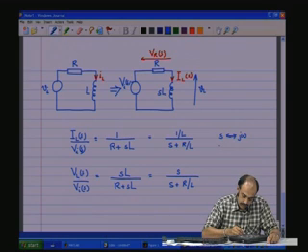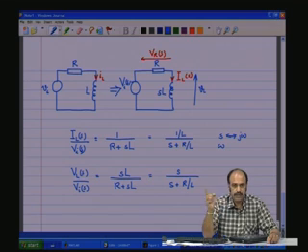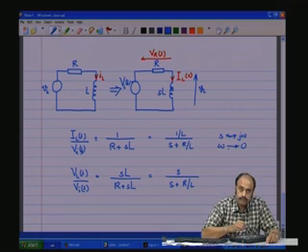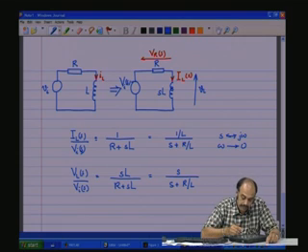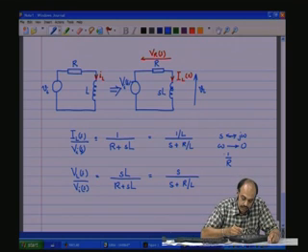So, when we give an input step, as it starts going towards the steady state, that is omega starts tending towards 0, that is pure DC, away from the transients, you will have 1 by R as the scaling in this case, that is IL by VI would be just 1 by R, or VI divided by R would be the gain.